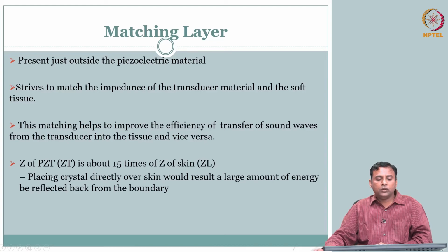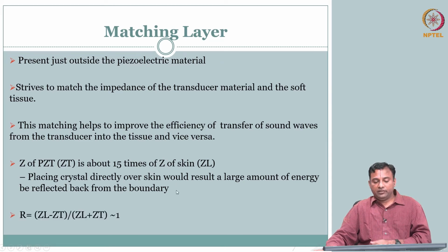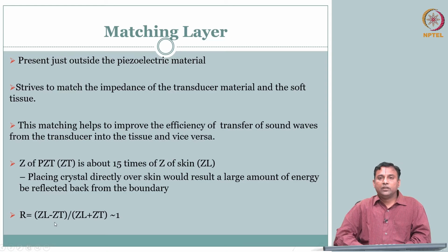Okay. So your PZT, so Z here is your impedance, right, not the zirconium Z that you have here. So Z is about 15 times Z of skin. So naturally, placing the crystal directly over skin would result in large reflection. Okay. So you need a matching layer for that.